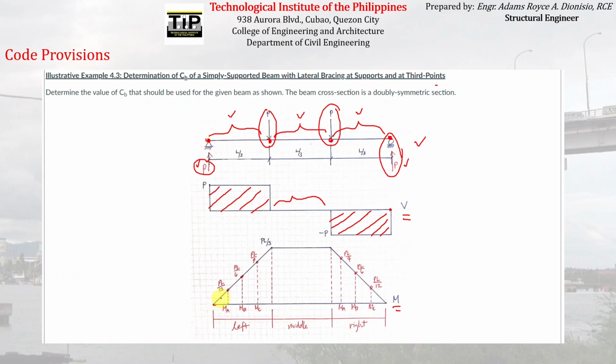And then go linearly from this point to this point, since this is a 0 degree shear force diagram, or shear diagram. The moment diagram, the corresponding moment diagram, must be 1 degree larger. So it must be 1 degree, or first degree, which is a linear diagram. On this particular point, there is no shear force, so the magnitude of moment there will be constant. But from this point, you have to subtract the area of this shear diagram. That will result to 0.